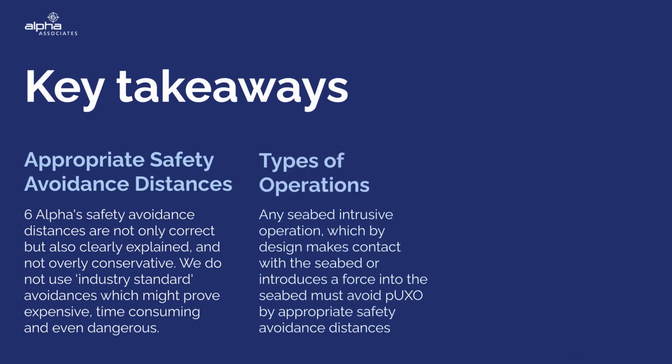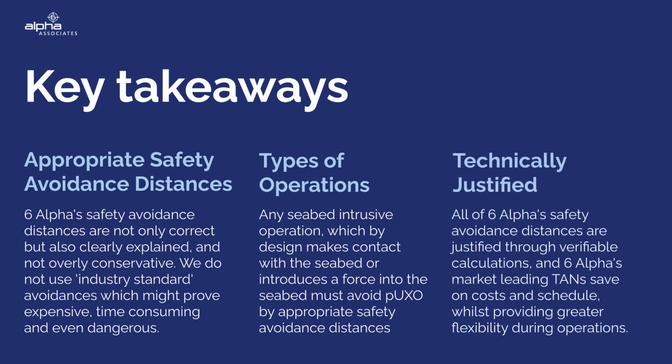Remember, any seabed intrusive operation, which by design makes contact with the seabed or introduces a force into the seabed, must avoid UXO by appropriate safety avoidance distances and can have these calculated on a case-by-case basis. All of our avoidance distances are technically justified through verifiable calculations, which is important to ensure the ALARP safety sign-off certification is compliant with the local jurisdiction as well as with best practice.